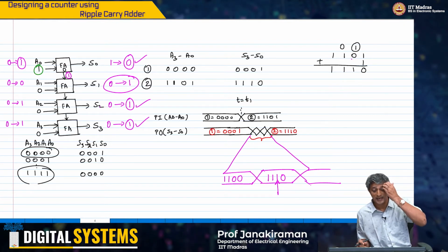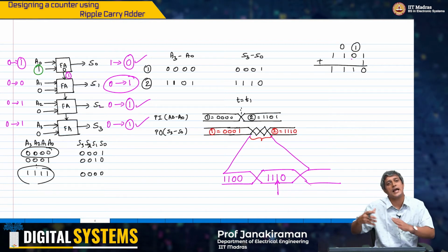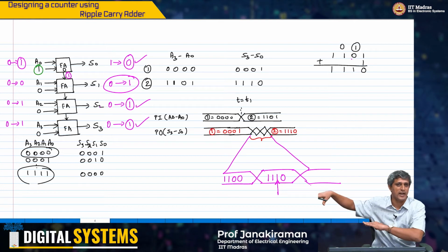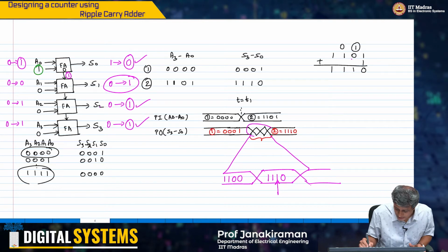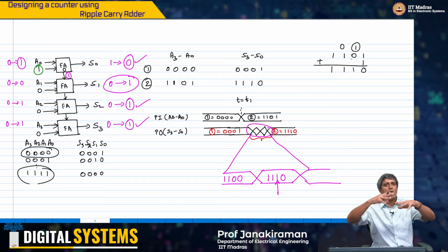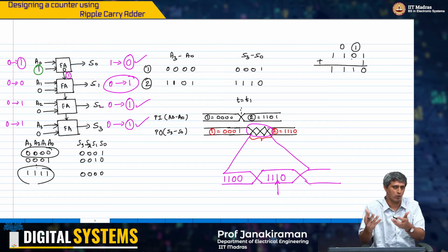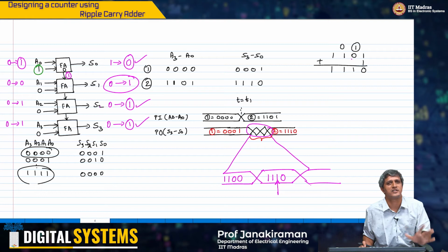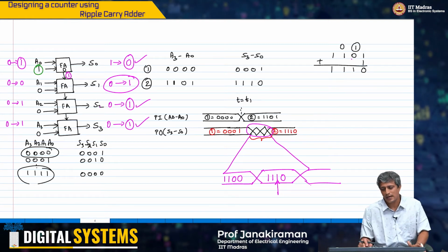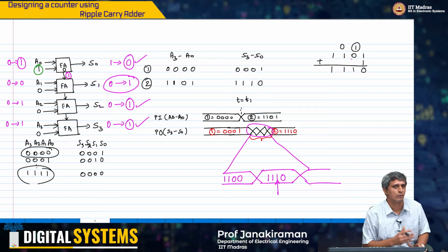Of course, the worst case is when the carry propagates all through and the delay is the longest delay. But I am just trying to say that when we draw such a thing, it means that at least one bit of the outputs, or inputs, whatever those set of bits are, is changing, but we do not know what they are, we don't care what that intermediate state is. Eventually it will settle to its final value, which is 1 1 1 0.